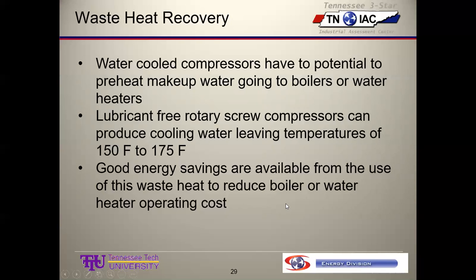So if you balance the water flow just right, you can get water temperatures of 150 to 175 degrees coming out of these compressors, which is pretty effective. You put that into a water heater. If you have a situation where you're heating water continuously, that can really back off the fuel usage, the energy requirement of the water heater, because you're already providing it with pretty warm water. Good energy savings are available from the use of this waste heat to reduce boiler or water heater operating costs. Said that a couple times.